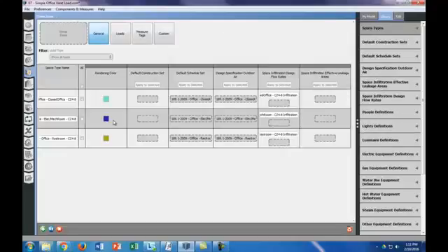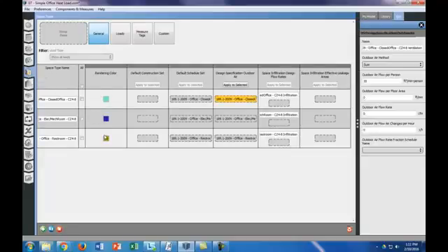The next thing we're going to do is only bring in 5 CFM per person in our example. So we're going to go to our space types here, and change the outdoor airflow per person to 5 cubic feet per minute per person, and you can see that we're going to do that for all of our spaces. The other thing to notice is that in the office there's no outdoor airflow per floor area, but in the restroom there is. That's just to ventilate the restroom, since we want to bring in fresh air to the restroom.